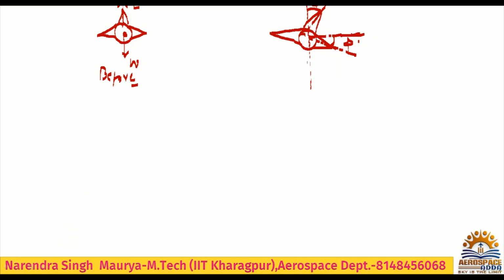Now obviously this will be the lift force, as in the previous case you have seen. If this is L, the weight will always be acting in the downward direction. But if it is banked like this, L will come here in this way. The vertical component will be L cos phi, and on this side it will be L sin phi. If it is turning, then obviously one force will appear, which is nothing but the centrifugal force, m v square by r.